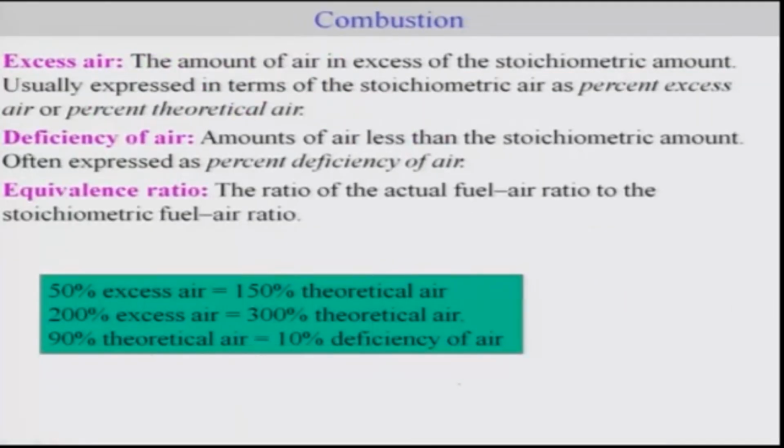Thus we define other terms such as excess air, which is the amount of air in excess of the stoichiometric amount, and usually this is referred to in terms of percentage excess air or percentage theoretical air. Deficiency of air is the amount of air less than the stoichiometric amount, often expressed as a percentage deficiency of air. Equivalence ratio, though not very commonly used, is the ratio of the actual fuel air ratio to the stoichiometric fuel air ratio.